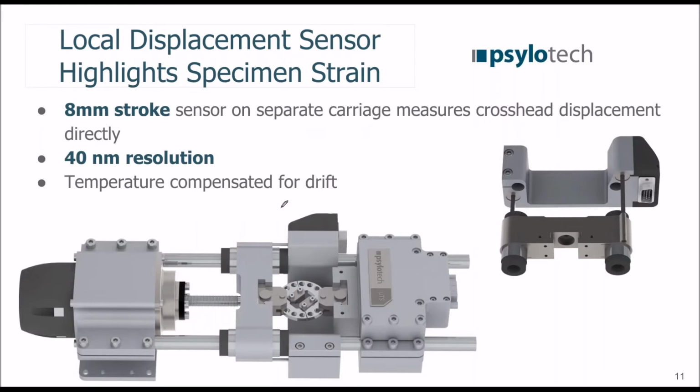Our displacement sensor is actually mounted right here. For DIC you're getting the ideal local displacement fields of your specimen, but sometimes you need more of a global displacement. Instead of using the encoder reading, which is what a lot of other companies will do, we have this displacement sensor directly mounted to the crosshead here. So we get an exact reading of the crosshead, which we can control off of.